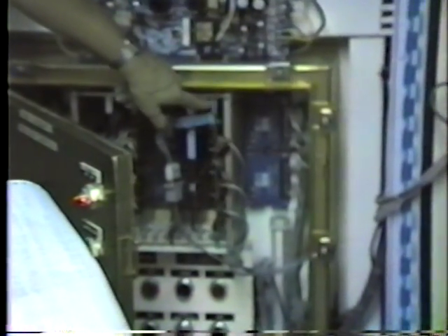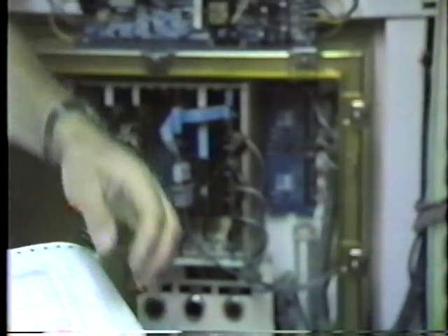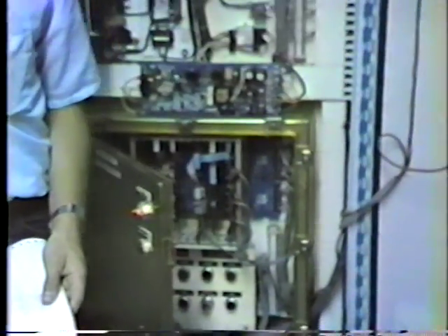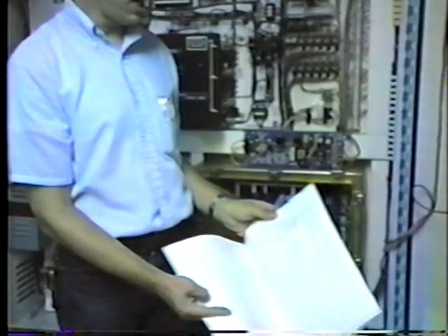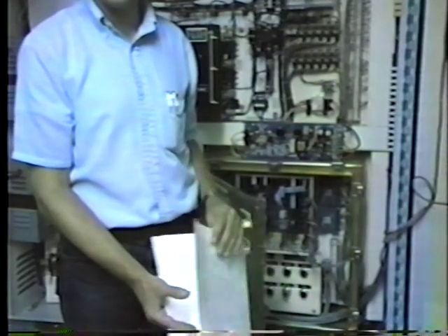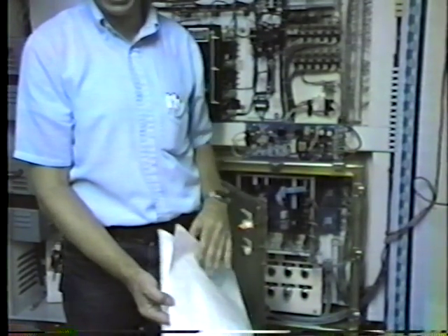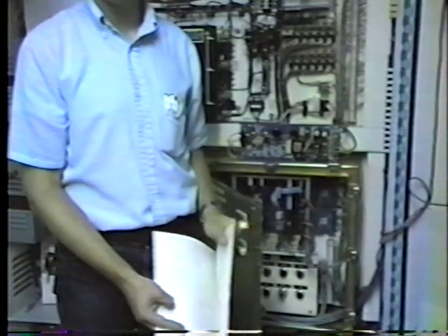What does the watchdog timer do? The watchdog timer protects us in case of a computer not failing hard, but going kind of crazy. If the computer does not, every time through its loop, say, "Hi, watchdog timer," in about 3 seconds, it will time out and reset the computer. This keeps the computer from going off into space. That's correct. Besides the watchdog timer, we check the random access memory by writing a pattern out there and reading it back. So in effect, the computer checks itself.